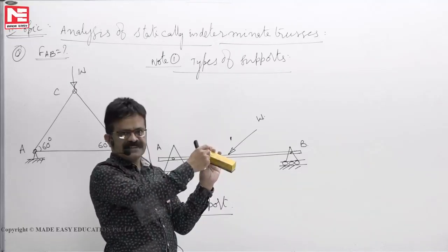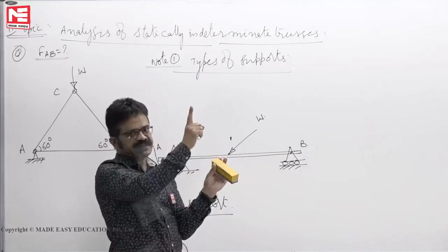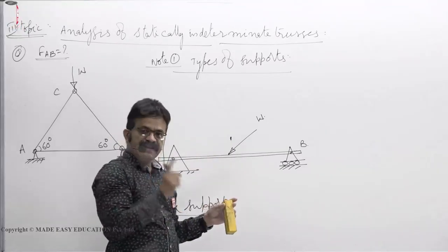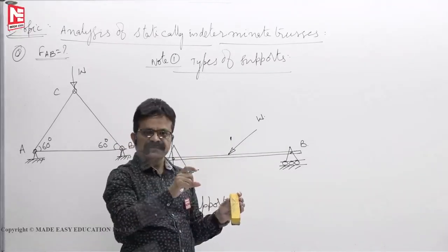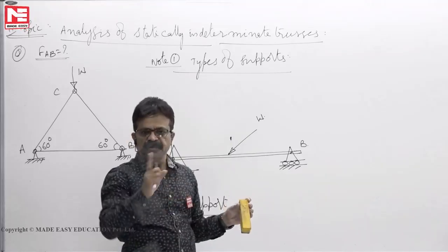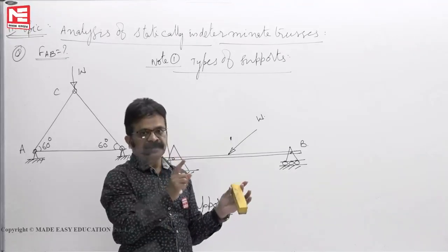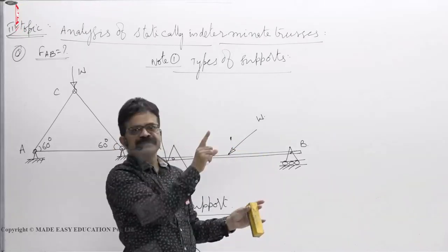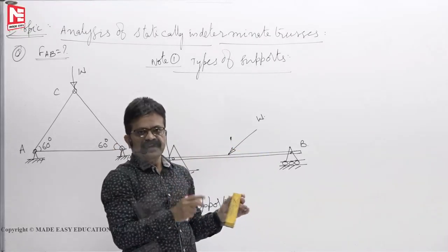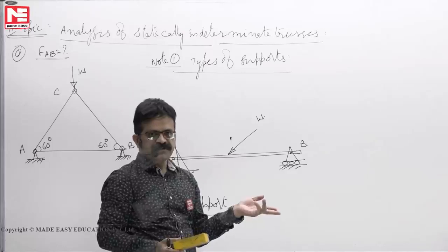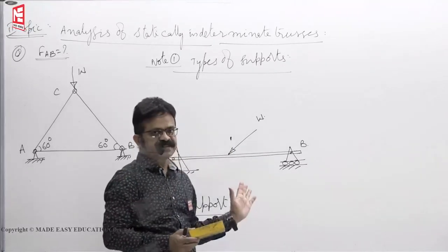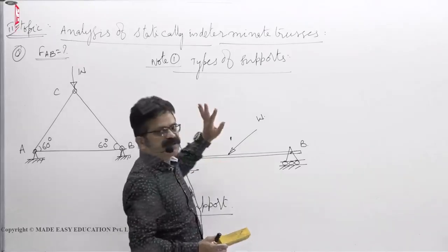Here and here double shear, then you can replace it by a single force. Resultant reaction we can say. And that single force cannot offer a moment reaction. To have a moment reaction, there must be a couple. A force here, another force somewhere here must be there, then it can prevent the rotation. Since the second force, which is not in line with the first force, is absent, it is free to rotate.